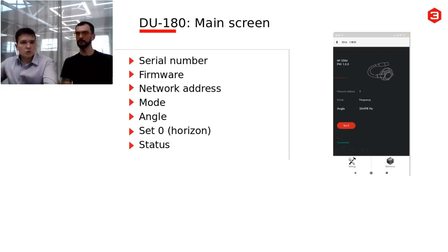And there are also modes for different trucks, for garbage trucks, for tipper trucks, for manipulators. For certain cases, you have to monitor the angle constantly. In other cases, you just have to set a critical angle, say 15 degrees, just to see if the tipper did a tipping operation, or if the crane actually has lifted the arm, or your excavator operator was just sleeping all day and didn't do any useful job. So that's one of the main ideas.